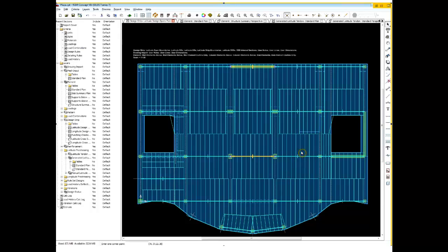You can see what's going on and take a look at where it generated those, because remember, they're automatically placed. You can make user adjustments to the cross sections, and there is a tool, maybe a little known tool, for adding your own design cross section through the slab. So you can manually define your own cross section if you like. Let's go to the perspective, because that's what I'm after today.